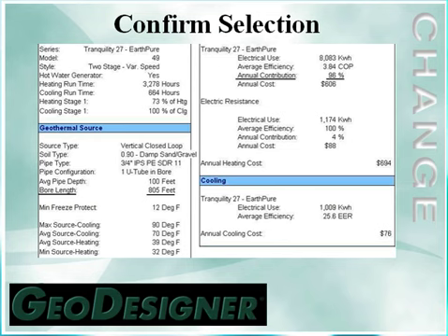Now, folks, I know we're all kind of like Tim the Tool Man, and bigger is always better, but do realize sometimes we can select a unit that goes so large, trying to cover 100% of the heating, that our operating cost actually goes up and our payback becomes longer, and we've actually gone to too large of a unit. So you can try a few different size units till you get one that hits that mid-90s range for total annual contribution.